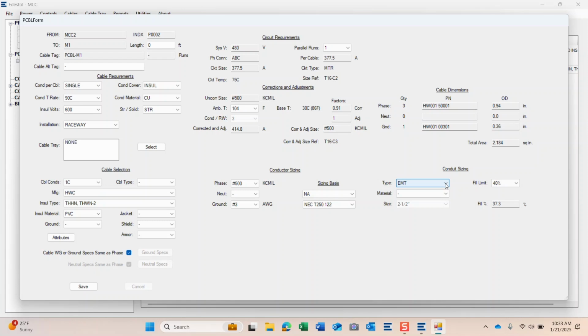So you have to remember, when the design is complete, the cable that connects to the motor will actually go from the disconnect. We're going to put disconnects in, and it goes from the disconnect to the motor itself. So in this case, we're going to specify a liquid tight flexible metallic conduit, and we're going to leave that there. So we'll stay with 3-inch, but it turns out to be a 29.2% fill.